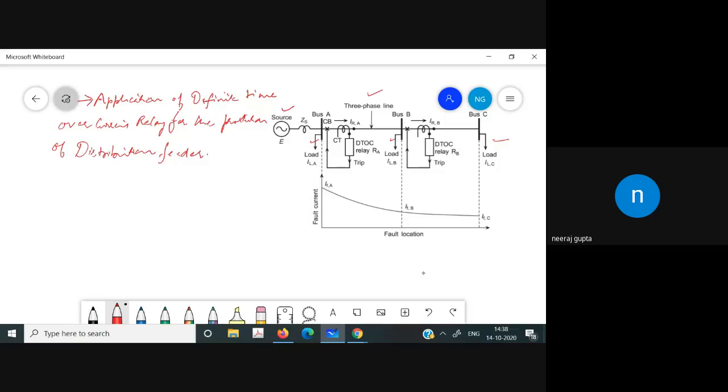If our system is balanced, the phases differ by 120 degrees. So we can represent it by a single line diagram, find the result for one phase, and get the other phases by rotating by 120 degrees. That's the main idea behind that.